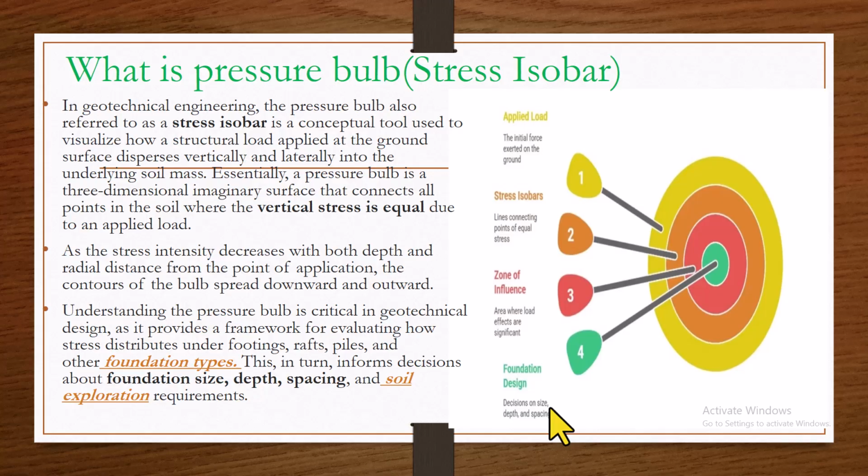So you see that it is very important for a structural engineer designing his foundation, because you have to be very careful of the size of footing. And also for a site engineer, you have to be very careful in monitoring them not to excavate more than required. But once you don't understand this pressure bulb, you will find it difficult to comprehend why you should not excavate more than the specified depth.